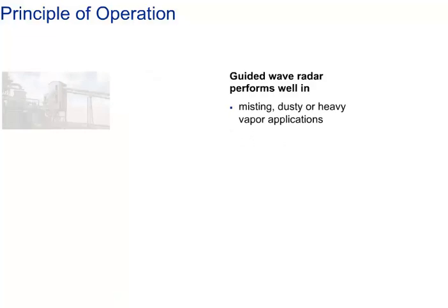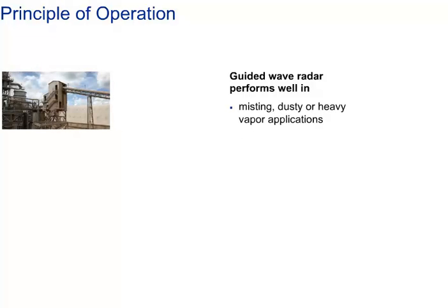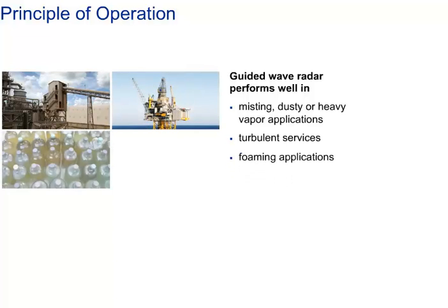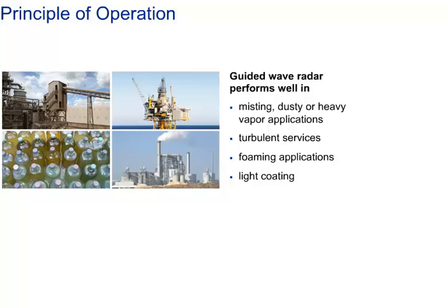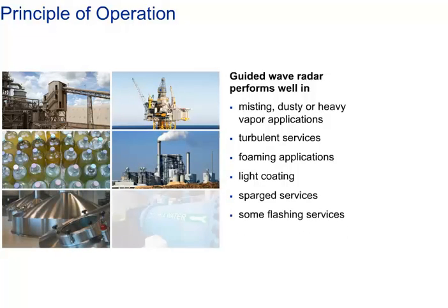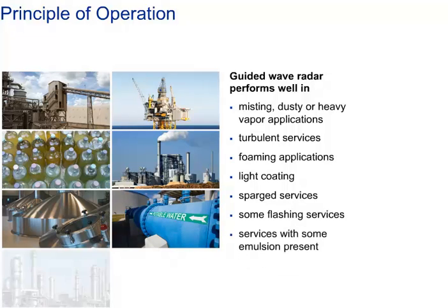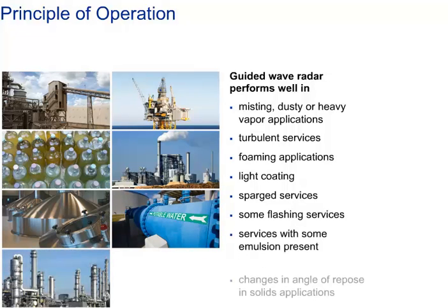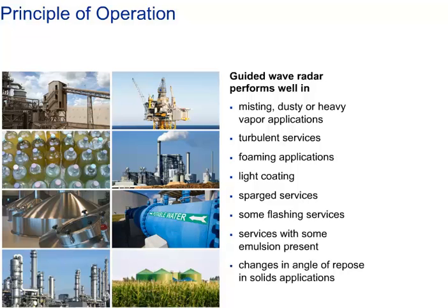Additionally, guided wave radar also performs well in misting, dusty, or heavy vapor applications, turbulent services, foaming applications, light coating, sparged services, some flashing services, services with some emulsion present, changes in angle of repose in solids applications.